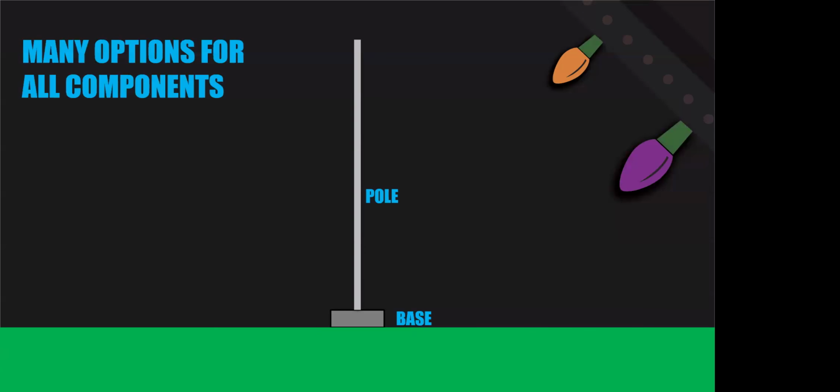Pretty straightforward. There's a lot of different things that people use for these poles, everything from fence posts to structural tube members. My recommendation is always go with the heaviest thing that you can find and afford and be able to lift. Fence posts, a lot of your piping that you're getting at the hardware store that's meant for electrical conduit, that is not designed to be taking compressive loads like you're going to be putting on here or the bending that's going to come from the wind.